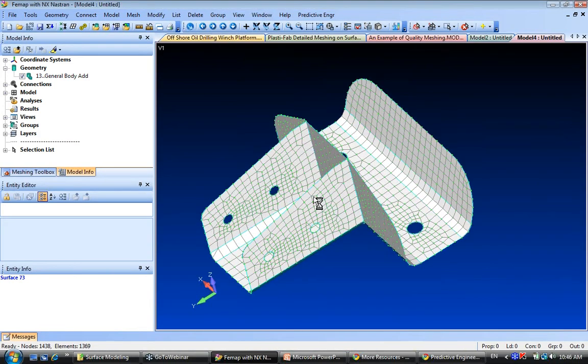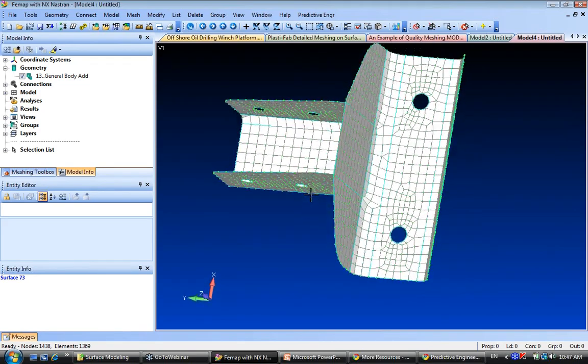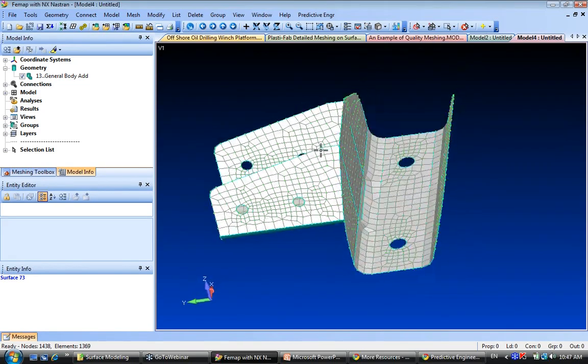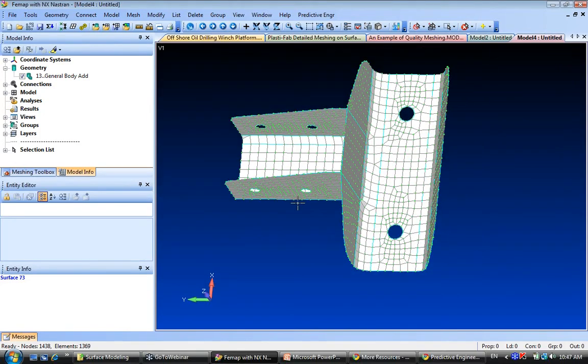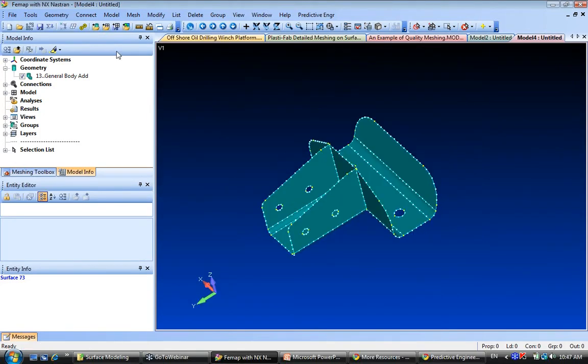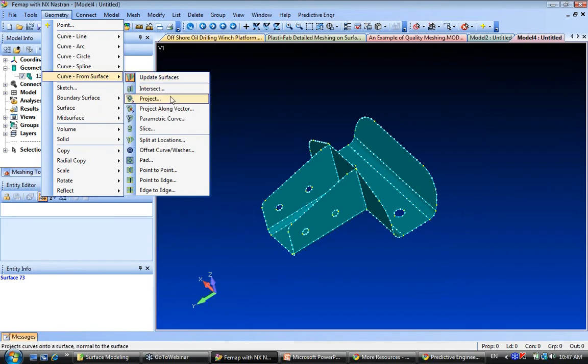And I'll do a lot of very simple stuff like this just to see how things are looking. It's not so bad. I mean, it's not ugly, but we can do a lot better. I'm going to undo, Control Z, and now I'm going to sort of force it into being a better mesher. And that is where you use all these. These are all your power meshing tools. With these, you can get away with everything.